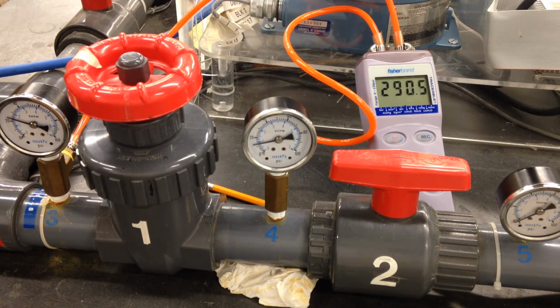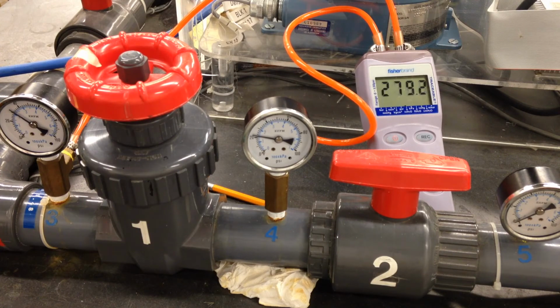We're going to open this thing at a quarter, a half, 3/4 and full. And I'm going to do something a little differently than I normally do. Because the rotameter is across the room from me, I'm going to let my video camera videotape whatever the rotameter is doing, and then I will take data points. So your data points are going to be a little arbitrary, as opposed to the nice fixed ones that we normally have in our report requirements. Don't let that faze you. I will tell you what opening we're at, and that's the way we'll do it. You just read the flows right off the rotameter because that's what they're supposed to be.